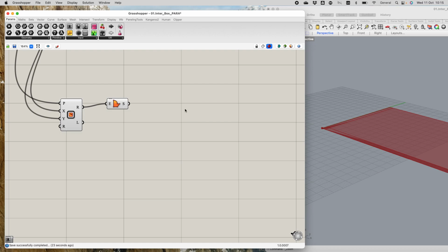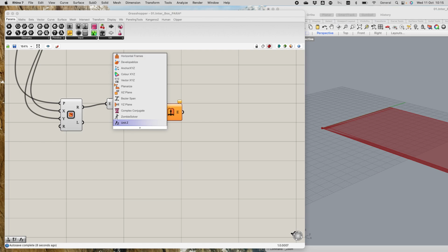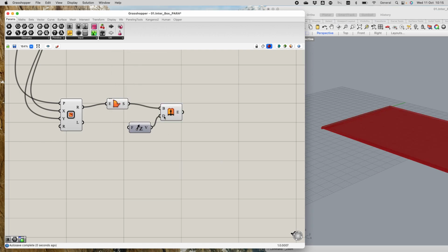And I want to give it an extrusion. So this is a straight extrusion. You can get other extrusions where you go at an angle. But the battery still remains with a warning signal. It needs a direction. It needs a Z direction because we go upwards. And whenever you are sure about a parameter, like the thickness of your cutting material, use a panel rather than a slider. Double click, and don't press return. You just type in 3 and that's it. Don't press return. So we have already our ground plane.